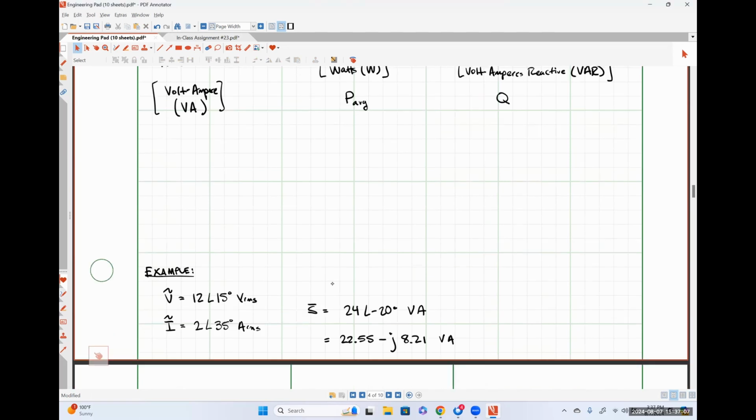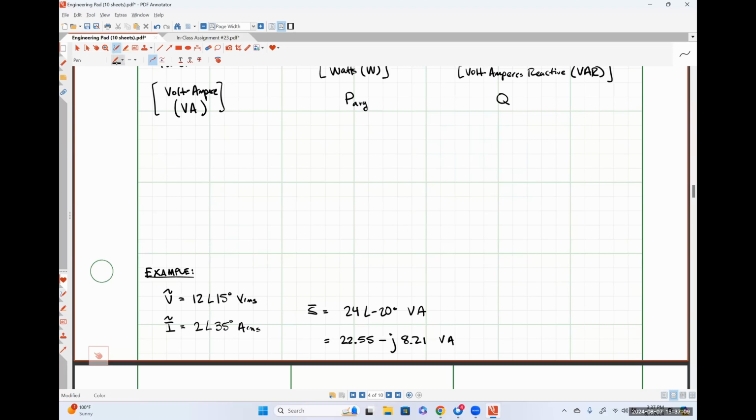So the calculation that I was expecting you guys to do was effectively 12 angle 15 degrees volts RMS times 2 angle negative 35 degrees amps RMS, because 2 angle negative 35 degrees is the complex conjugate of 2 angle positive 35 degrees. David, did that answer your question?